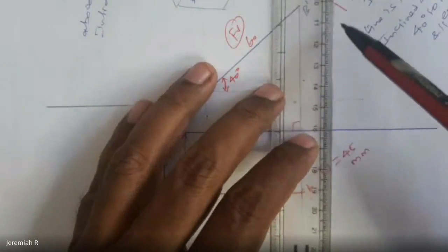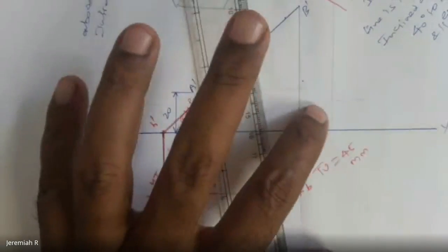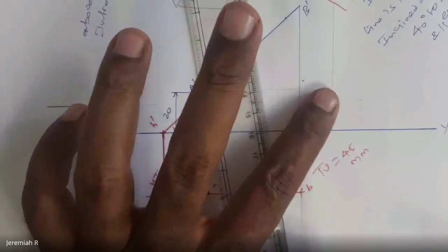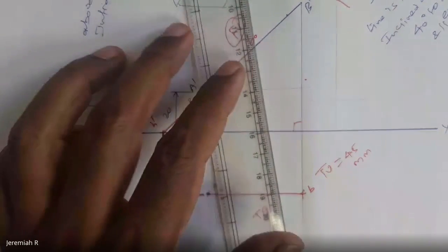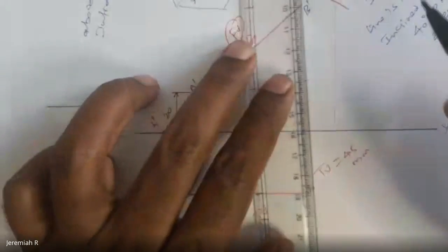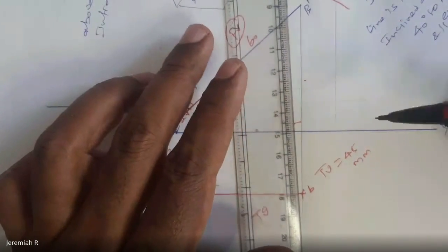Apply very little pressure. Just see here. So what I'm doing here? I drew a line here, but it is very light. So that is a method. Otherwise, you can use a 2H pencil or 3H or something like that. If you use a 2H or 3H pencil, you get very light lines, but if you use HB, 2B and all, you get darkened lines.